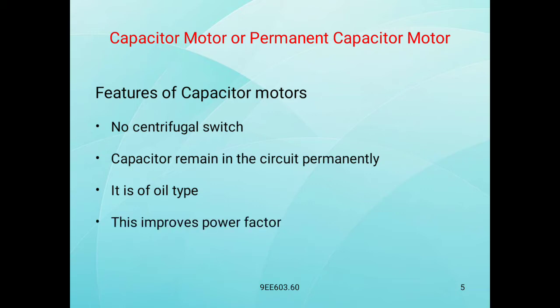This improves the power factor. So once again, the features of capacitor motors: no centrifugal switch, capacitor remains in the circuit permanently, permanent capacitor is oil type.